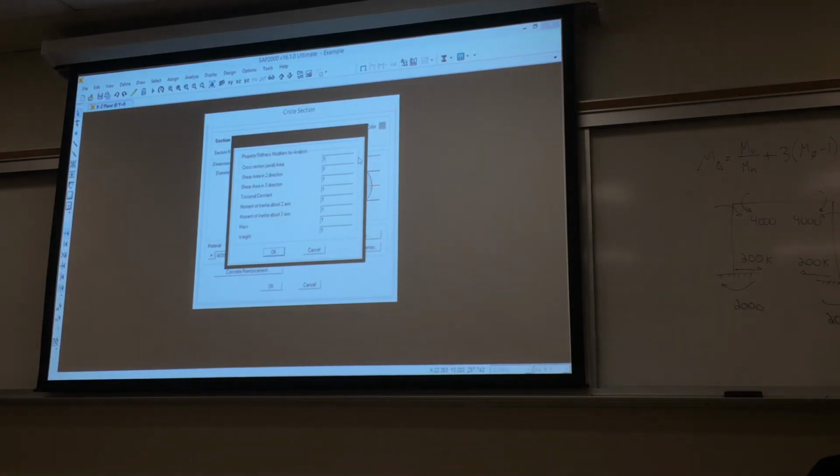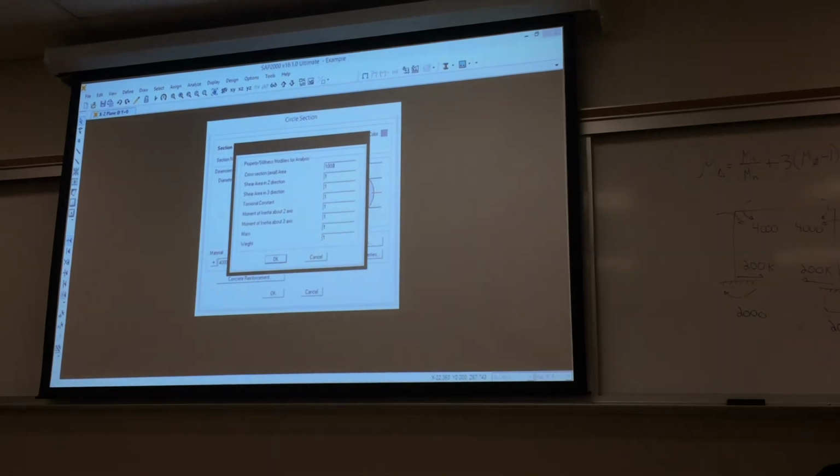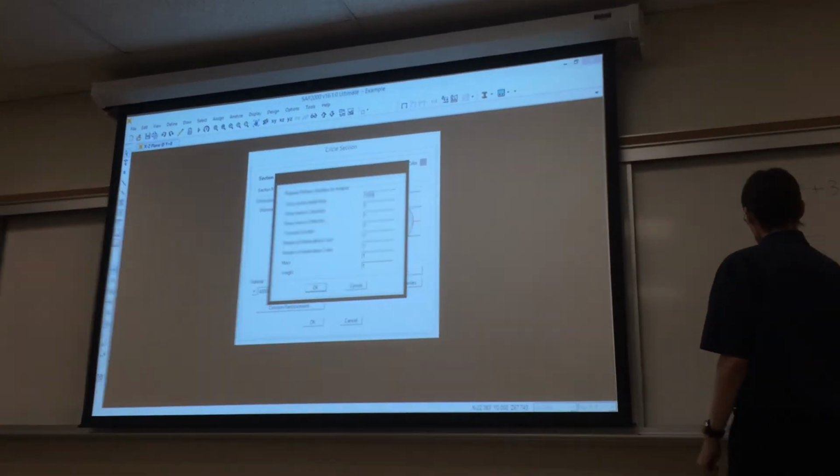So to get away from the axial deformation problem here, I can just, let's say, make this member really stiff. How stiff? I'm just going to use a factor of 1,000 here. But you've got to be a little bit careful with this, because remember I said at the very beginning of this class, this is a stiffness method solution. So the way finite elements are solved is using stiffness method. And that takes into account,